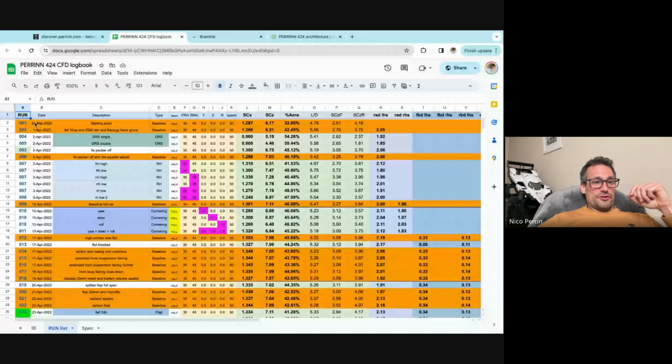But in March 2022, we restarted CFD in the Bramble platform. If you look at the L over D, it was 4.8 here for a drag of 1.28. That was the first Nürburgring specific starting concept, if you like, taken from the LMP1 Le Mans, and just adding the bigger rear wing and the new diffuser, and then starting CFD.